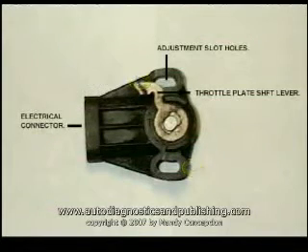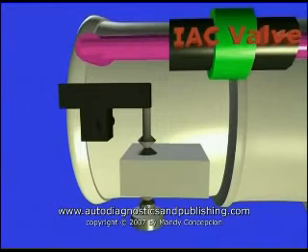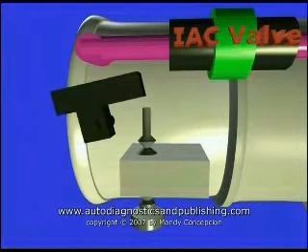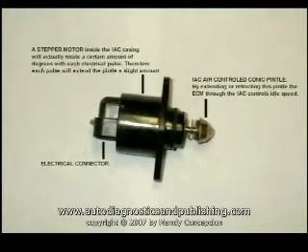The IAC, or idle air control valve, is another component involved during the minimum air rate adjustment. Seen here, at the upper part of the throttle body, this simple actuator controls the idle speed by letting a specific measured amount of air pass the throttle plates. Typical problems associated with the IAC are stalling conditions and idle control problems.